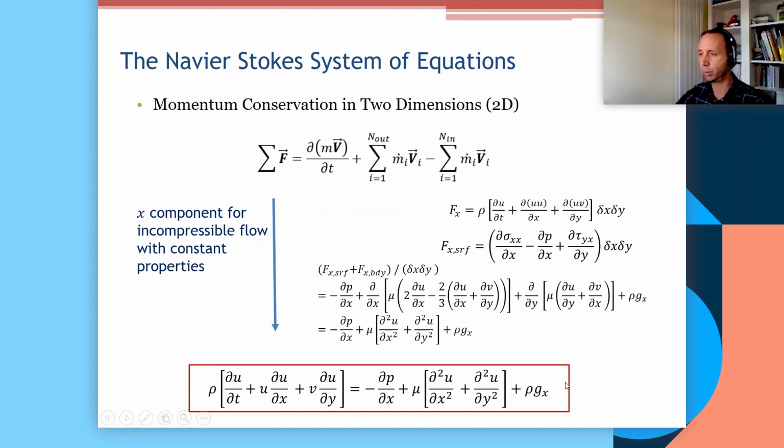So that's an expression of momentum conservation for an unsteady, incompressible fluid flow, which has constant density, I should say, and constant viscosity. The first thing you should see when you see an equation like this is the complexity of the mathematical representation, but you should remove that layer of abstraction and zone in on the physical meaning. We have a pressure force, a shear stress acting on the fluid, and a body force. The combined effect of all these forces leads to a change in the linear momentum, expressed in terms of a time rate of change of velocity and a change in the spatial distribution of velocity.